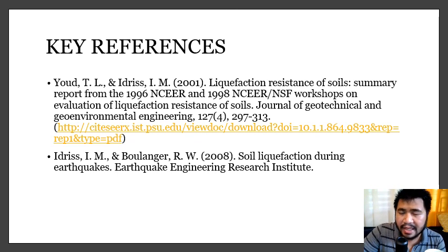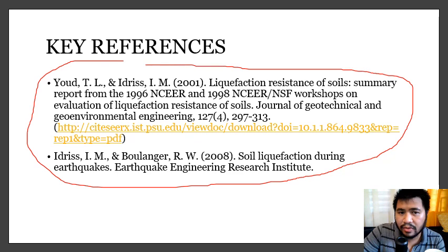To be able to do liquefaction analysis, just read these two references and you will understand the whole process and theory behind them. You have here Youd and Idriss 2001. This has a good discussion on how to do a soil liquefaction analysis, and this is the whole basis of my lecture. You also have Idriss and Boulanger 2008. They also have a good example on how to do the analysis and also how to do a settlement analysis, which will be discussed in the next lecture.